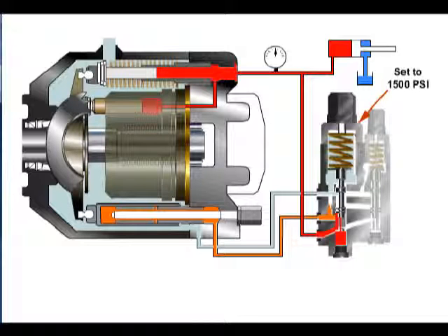With the swash plate vertical, the pump is now de-stroked and the pressure at the outlet port is maintained at a constant level. A very slight amount of flow is produced to maintain de-stroke pressure. This flow is bypassed into the case and carried back to the reservoir through the pump case drain outlet.